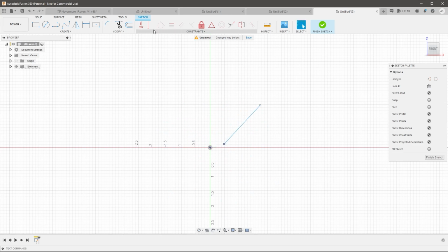If you didn't want to drag it, you can always come up here and hit coincident and then choose each point individually and achieve the exact same thing. So now that we have that point locked down, we either need to define where the end point falls, or what direction this line is pointing in. So oftentimes you can hit the horizontal/vertical constraint, and it'll snap to whichever it's closest to. So if it's closer to vertical than horizontal, past a 45-degree angle, it will snap to that. Since that was closer to vertical, it snapped to vertical. But if it was closer to horizontal, let me click that, it'll snap to horizontal.